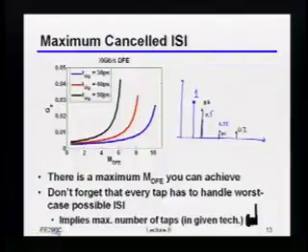Maybe I'll just ask you guys since I don't think you actually have the slide. So we said that one of the big problems here is that I have to deal with this worst-case condition over all possible channels. And we said that particularly in the DFE, because I have to close this loop so quickly, having all that extra parasitic cap is a bad problem. So what's a technique that we already learned about that you could potentially use to make things better from the standpoint of the DFE, and in particular from the standpoint of reducing the parasitic cap on that node?